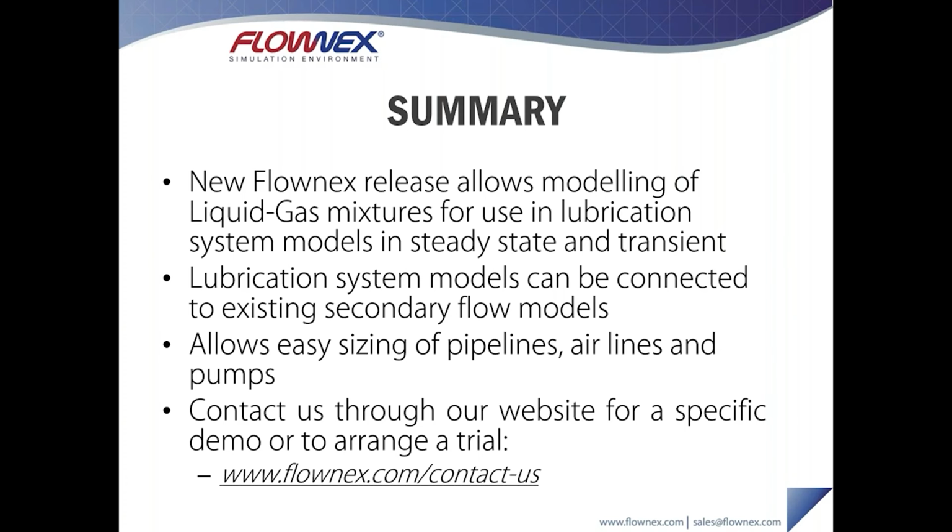transient. These lubrication models can be connected to our secondary flow models, so we can actually have the actual inlet pressure for our lubrication model calculated with the secondary air system and have the mass flow rate of air consumed by the lubrication system calculated by our lubrication model and sent to our secondary air system. So both of these models can be modeled in Flownex and solved simultaneously.